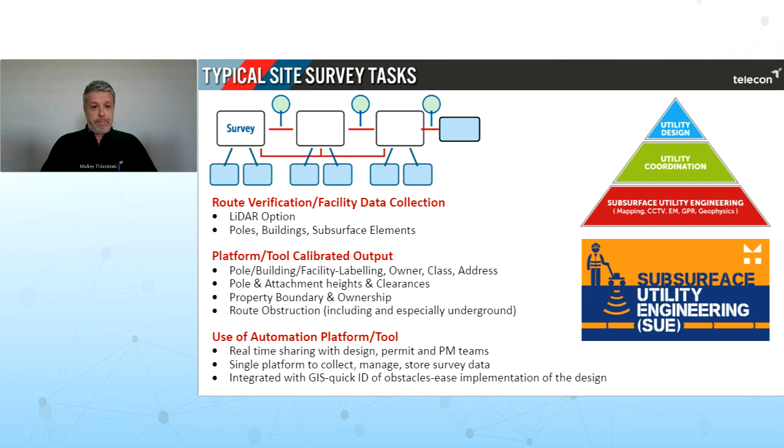So here's a good tip here. If you're using a real-time data source, Catapult or Esri, for example, assign an in-house office QC team to review that data immediately. Because our best practice is we'll QC the data from the field in real time, and we'll use automation tools that we've developed here. But you can provide feedback instantly if there's any changes or corrections required. And this will save you time on schedule, so you don't have to send them back to the job area after they've already left to go fix an error or something missed.